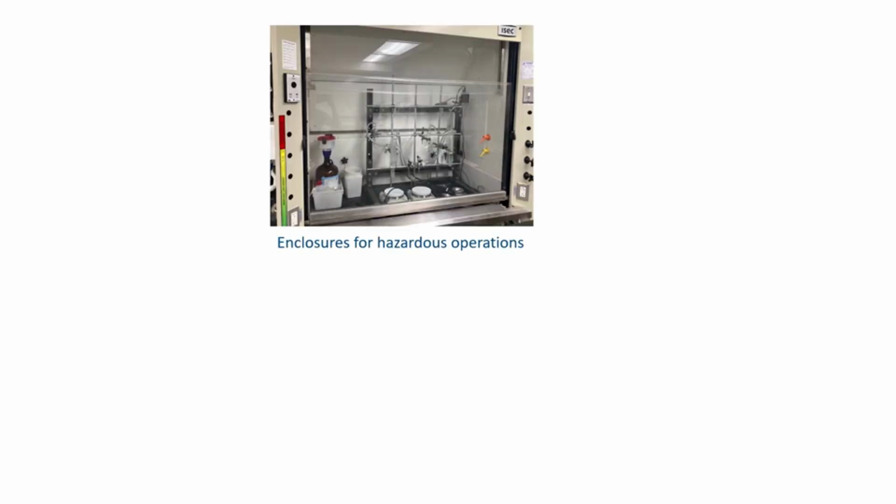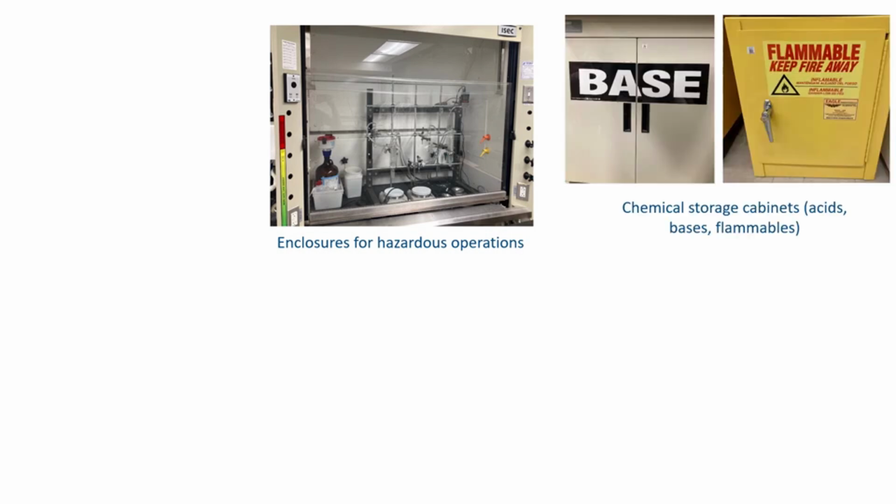Let's now look at a few other important examples of control measures in the workplace for the prevention and mitigation of toxic chemical exposures and other hazards. A first example for the prevention of exposures would be enclosures for hazardous operations. So here as an example, we see a chemical fume hood, which could enclose a hazardous process. It would also include ventilation, as we discussed in the previous slide, for the removal of toxic or hazardous vapors.